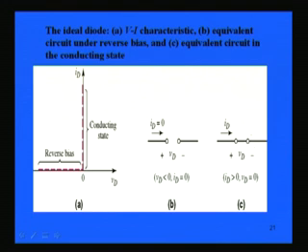That means the ideal diode has this type of characteristic that we can just assume it is like a switch. Under reverse bias, it is like an open switch, open circuit. Under forward bias, when it conducts, it is like a short-circuited switch because the voltage drop is 0. When it is under reverse bias, current is 0; when it is conducting, the voltage is 0. This is just a theoretical diode which will help in further analysis, that is why we are bringing in this ideal diode.